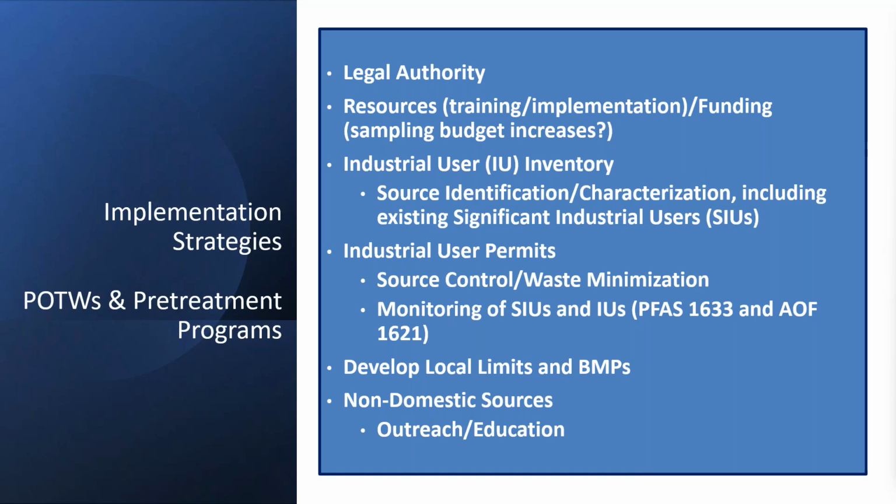You're also going to want to use your industrial user permits as a way to address PFAS, both monitoring and control of. And also, as you recall in Gene's slides earlier, a lot of folks noted that their largest PFAS problem was residential. Studies show that nearly every type of influent stream going into POTWs, which includes residential, contains some level of PFAS. So industrial pretreatment PFAS limits will have a significant impact, but they're not going to eliminate all of the PFAS from POTW discharges. Next, Gene.